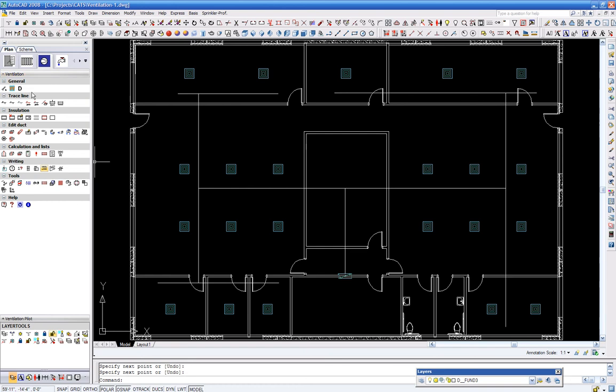Once our center line is completed, under the Task Commander, under Ventilation, select under Traceline. Repair Traceline Global. After selecting the center line, we are creating a trace line. Now we are connecting our diffusers automatically to our trace line. In the AutoCAD command, we are asked to select the diffuser. In this case, we select all diffusers.